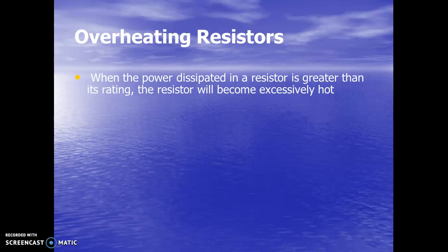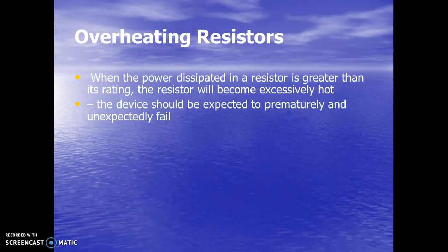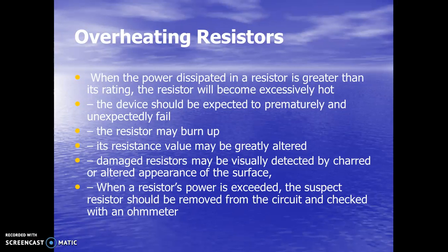One of the things that is inconvenient about resistors is that, unfortunately, as a resistor gets hotter, its resistance goes up, and so we have to accept that there's some variability in our resistors as they get warmer. And this also means, of course, that we don't want to get close to its maximum power rating.